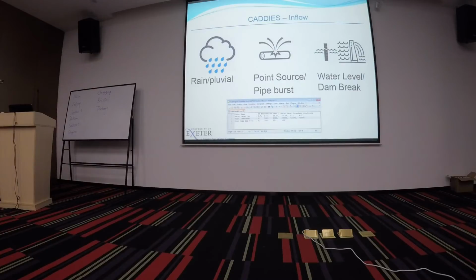And then I say water level or dam breaches, where we raise the water level to the given point, allow that water to leave, and then we replace it back up to the specified level, because the water behind is replaceable. So a similar sort of setup here, with an arbitrary name. This one is actually a water level event. So we need to specify a zone, an area for that to be applied to, which is true for all three of them. So we need to specify a point or a box.